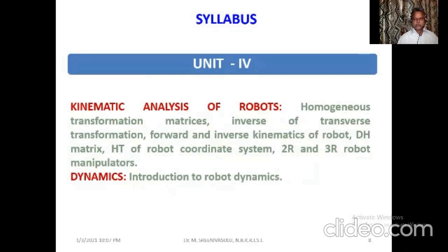Whereas when you want to have interaction with the environment, when the robot is moving, that time it is always recommended and better to keep the data in Cartesian format, which means that the data is actually required in both of the schemes, joint space scheme and Cartesian scheme. There is a connectivity between those two. That information can be transformed from one form to the other.